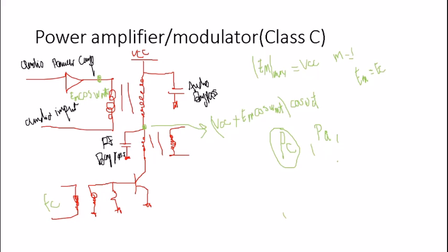Secondly, we can find out Z output, which is the impedance that can be seen from the power amplifier and the impedance of the transformer. The only reason why we want to find the impedance right here is to perform power matching between the audio amplifier, which is right here, and the impedance of this audio transformer.